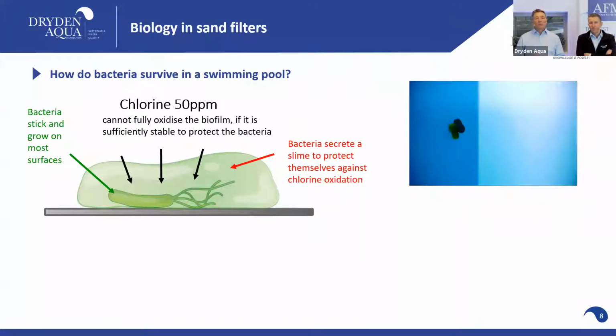And if you go, of course, with 50 ppm of chlorine in such a biofilm system, you will remove 99.9999% of the biofilm, but out of 1 billion, you will always have a few that will survive. The superbugs, the very strong bugs, the James Bonds of them, and they have then all the food and all the nutrients available, and then they can grow and double again.